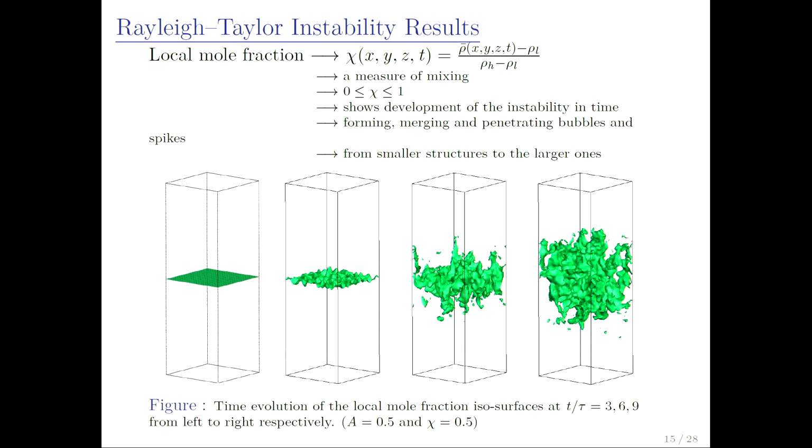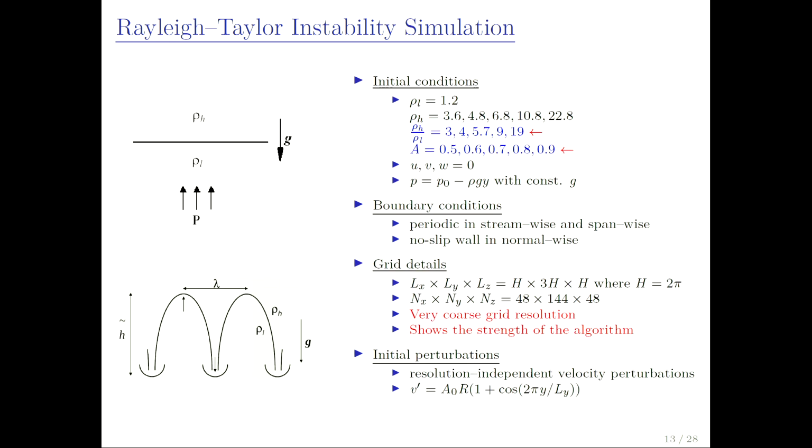So here is the evolution of the flow. By the way, I forgot to mention that the Atwood number I'm working with goes from 0.5 to 0.9. In some papers, this is called the ultra high Atwood number region. Are you doing miscible or immiscible fluids? Miscible, of course.